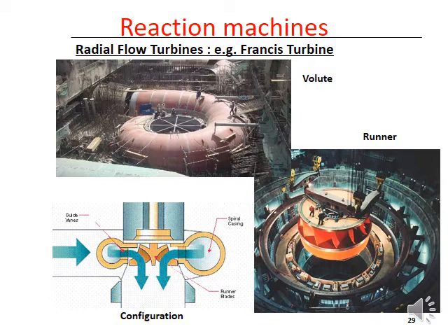They are all rotodynamic type. We also have impulse turbines. Like Laxapana, we have Pelton wheel turbines. They are impulse type turbines. Like Victoria or Randenigala or Kotmale power stations, you can find reaction type turbines.